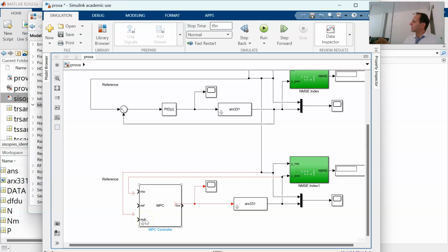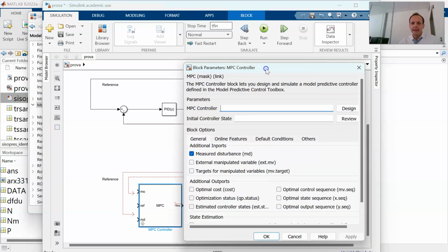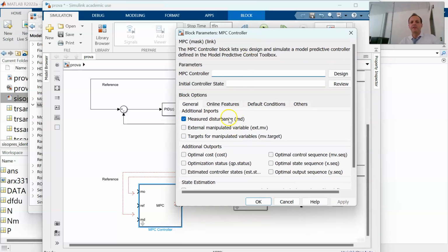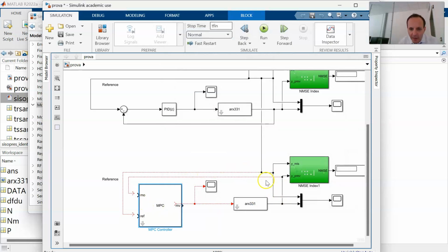It is represented by the equation error that we are generating with the recursive least squares approach. But this time, just click on the block and in the mask disable it. You can see here, you can add other inputs. We can comment on it later. So we can remove the measured disturbance because at the moment we are assuming that it is not available. So apply, okay.